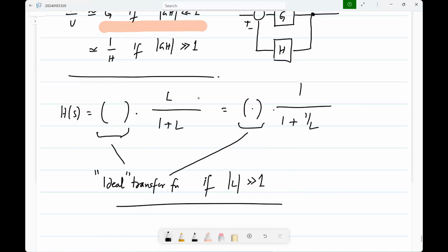We'll see. But first of all, this business of continuous adjustment of the output naturally leads to the integrator, right? So this amplifier without any delay or without any phase shift doesn't even exist. Okay. So this continuous adjustment naturally leads to the integrator. That's why I like that. But we'll see what happens. You cannot anyway have amplifier gain with no phase, that's not going to happen because there will always be some delay. Okay. And I think you already studied the effect of having too many poles, coincident poles, and so on. Okay. So stability will come into the picture. So we'll continue from there. Let me stop here at this point.